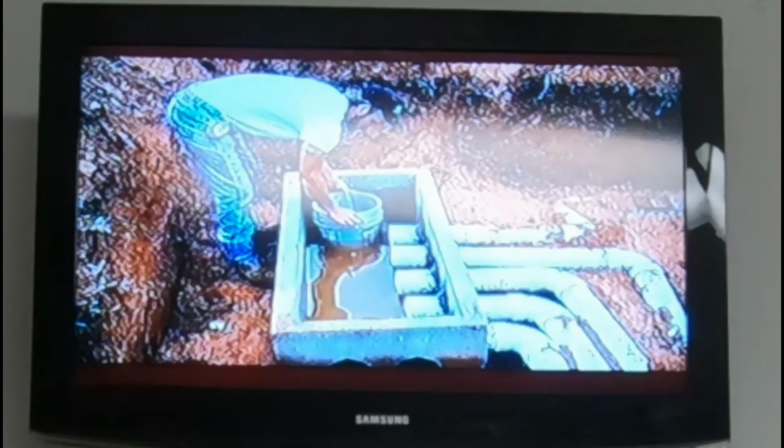Installation of the distribution box shall be made to provide equal flow to each absorption line extending from the box. This is done by making sure the box is absolutely level. The best method of leveling a distribution box is by filling it with water.